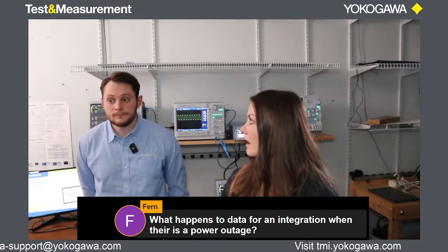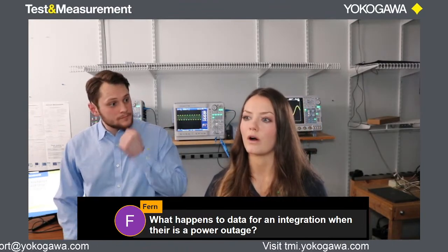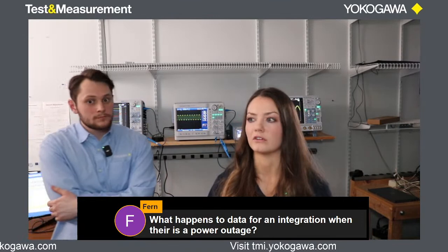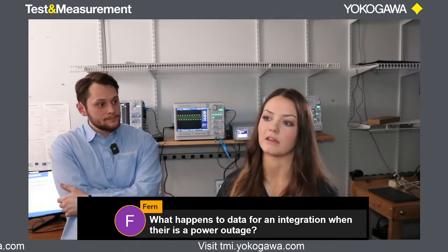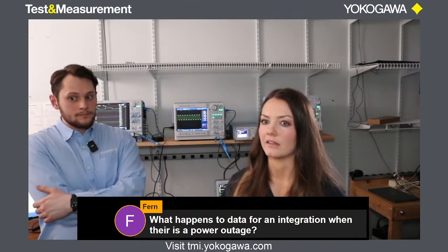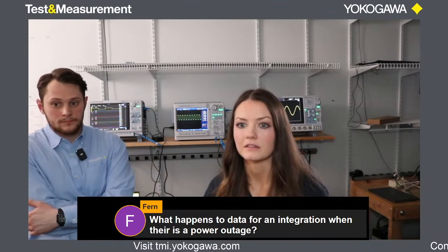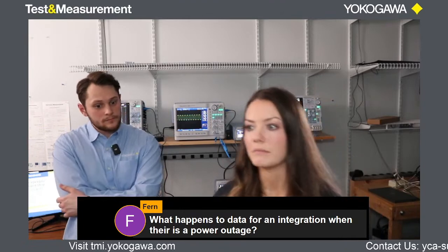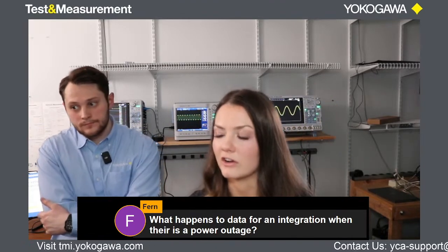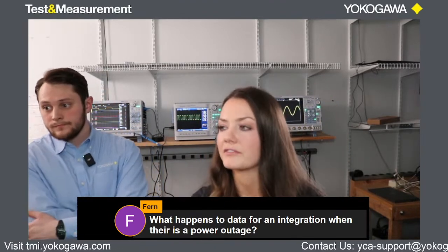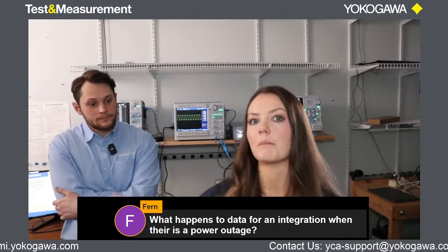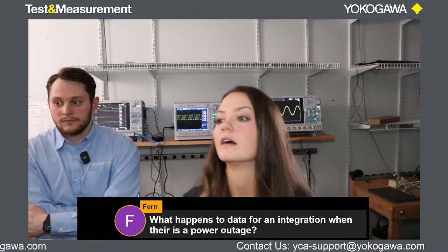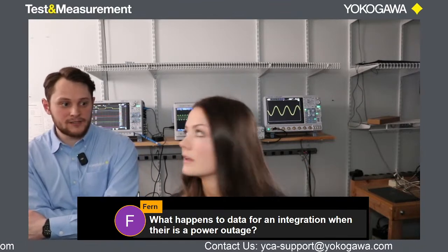Yeah, and with the integration, when you're setting up integration, which I guess we can explain a little bit. Essentially, if you want to calculate watt hours, say you're doing standby power or something like that, and you want to calculate watt hours over time, that's what integration is doing. So you can press start for that, and it'll start counting up voltage, current, power. So that's kind of like a time base for your calculations.